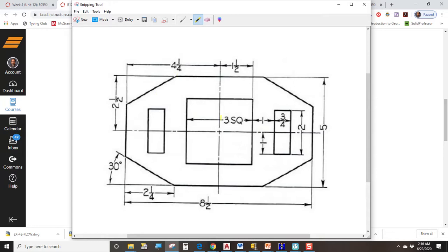So people have different strategies for drawing. I'll show you my strategy. I think whenever you see a drawing with center lines, the center lines are like the skeleton of the drawing. And just like your body needs a skeleton in order to stand up, the drawing needs a skeleton to get started. Okay, so what I would do if I were you is I would draw this center line and this center line as my very first actions. Okay, and once you have the two center lines on the paper, well, you know, the rest of it's going to be pretty simple, I think.